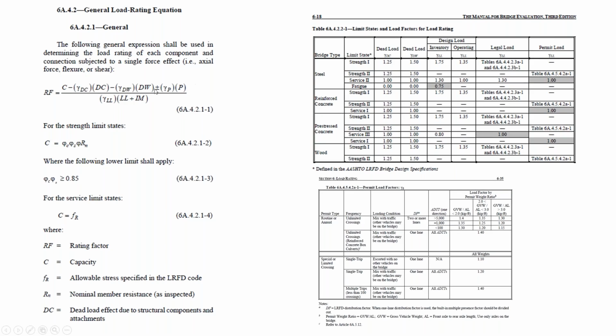and also accounting for the post-tensioning. And that is divided by the live load, so that we find out how much live load capacity we have over the actual one that is specified. So if the rating is more than 1, everything looks good, no problems.